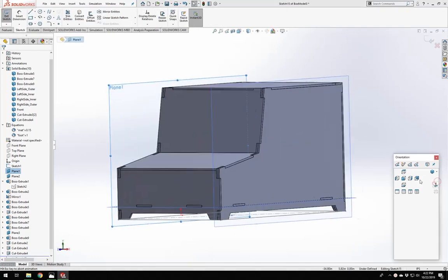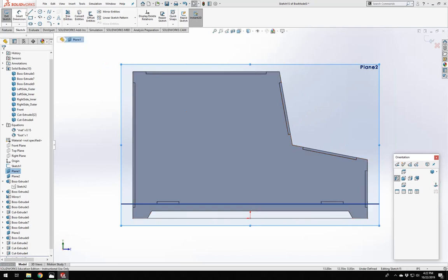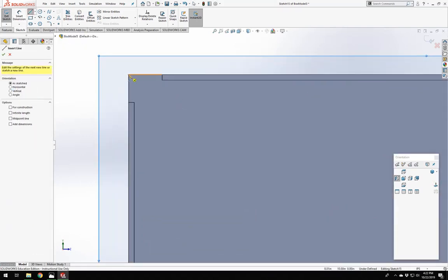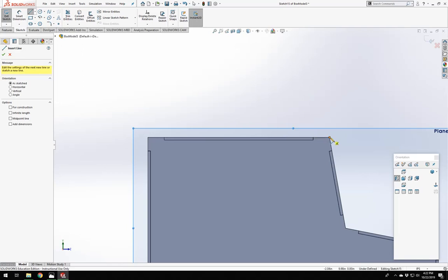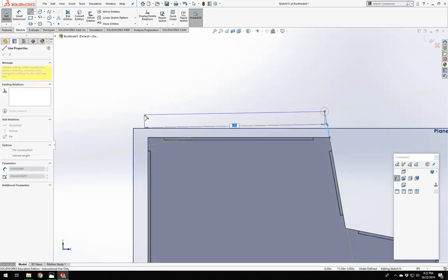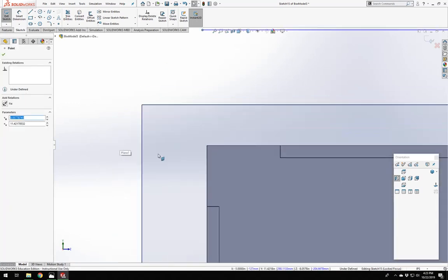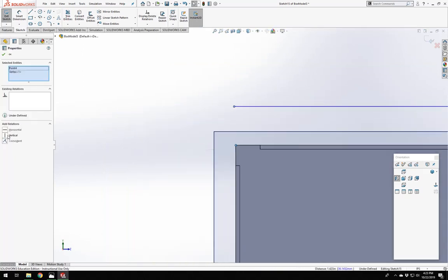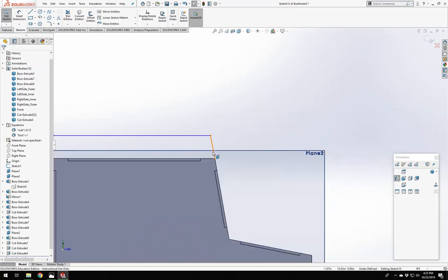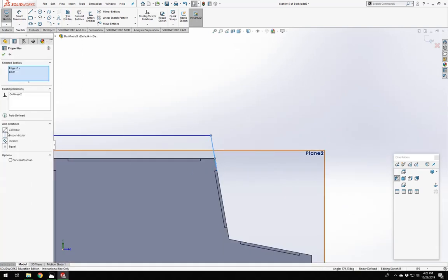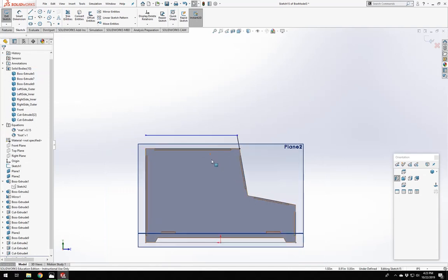Do a sketch. Flip it around. So our lid, we're going to start the front. Sort of like this. But we're going to do something slightly different on this back edge of the lid. So let's line that up first. There we go. We're going to make this collinear with the front. So the angle when it's closed is the same.